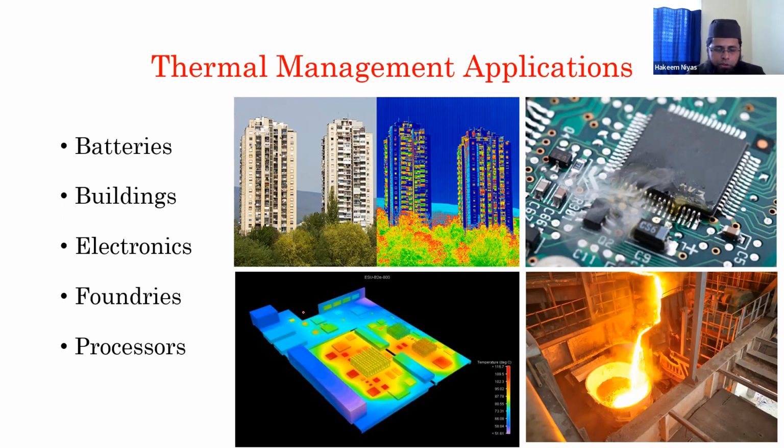And of course, batteries I have told, and electronics. You can see that the temperature in certain areas is, for example, even 116 degrees Celsius. But the threshold temperature in most electronics is about 95 degrees. That is the maximum temperature that can be reached. And the safer operating temperature is 75 degrees in many of the latest equipment.